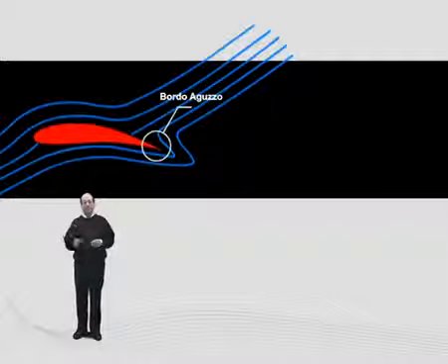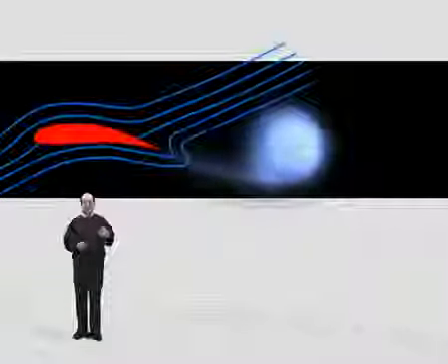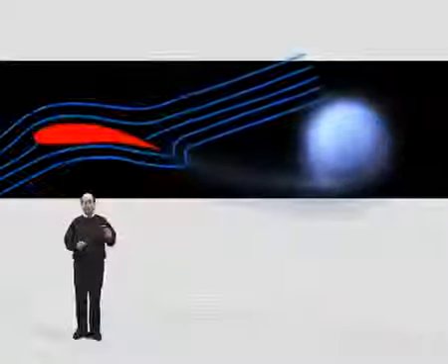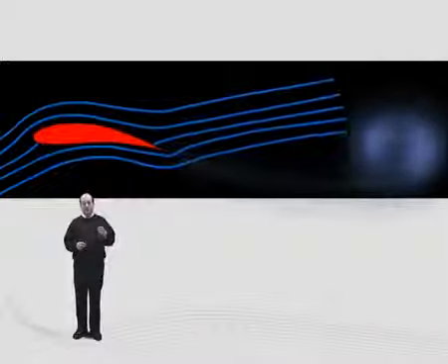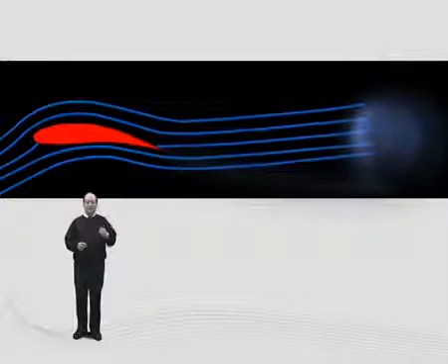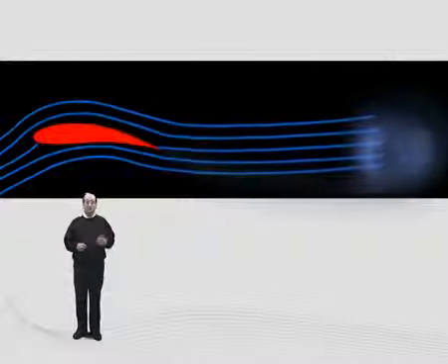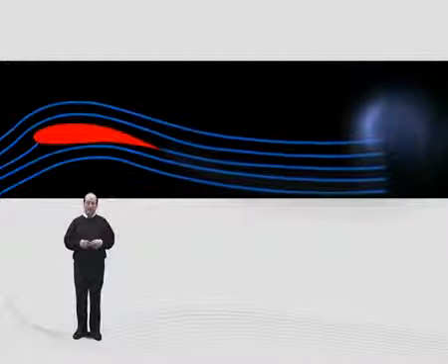The motion of such a body in a real fluid produces tangential forces due to friction in the boundary layer and in the wake. These tangential forces make the fluid rotate. When an airfoil begins its motion, the fluid tends to turn around the sharp trailing edge. Since a very high velocity is needed to turn around the trailing edge, the flow separates and forms a counterclockwise vortex. This vortex is initially unstable, and after a few times, it is taken away.